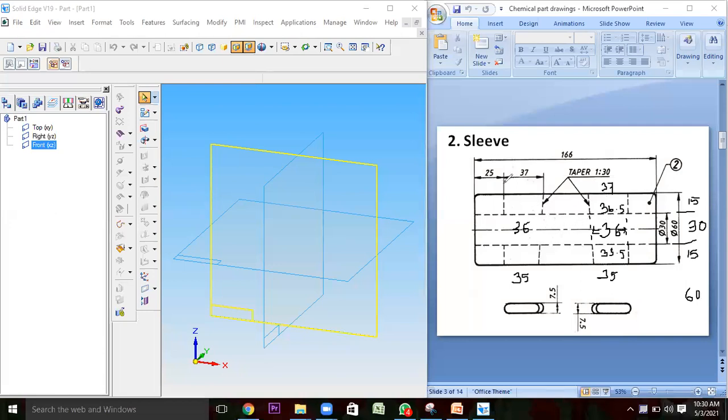And the sectional view over here, it is given here, it is from this end 25 mm, and also the same thing will be over here, because it will always be having symmetry. Most of the time if the dimension is given only on one side, then you should consider that you can do the sectioning over here like this, like bisectioning or sectioning it half.